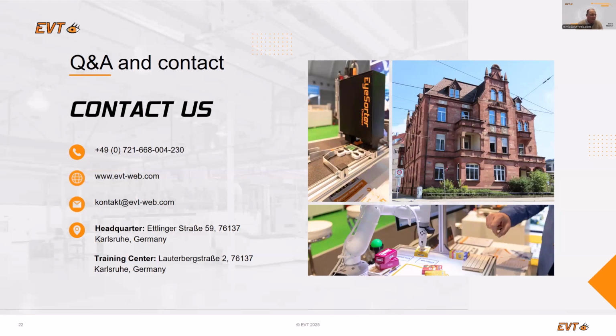The selection of the cameras is built in the software. So after the download, you simply can select in the hardware configurator which hardware you want to use. This belongs also to the MIPI interfaces. If you use an embedded board with a MIPI interface, like, as I showed before, the Raspberry Pi, but also NVIDIA or Orange Pi or whatever, you can select, in that case, Video for Linux. This driver will support the MIPI camera interface so that it's very easy.